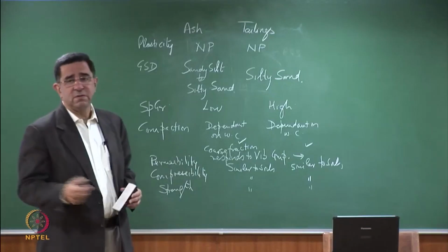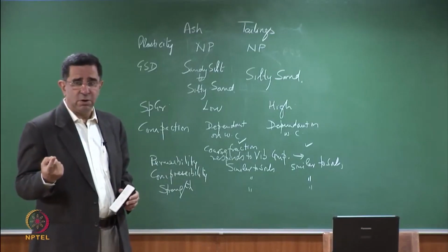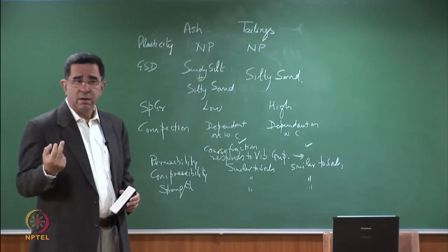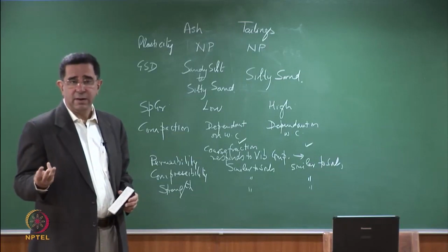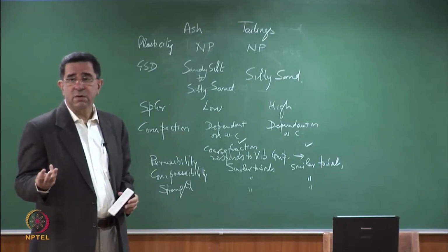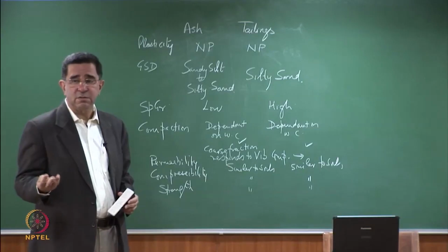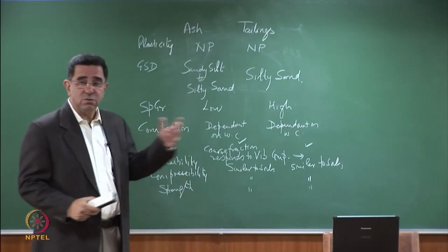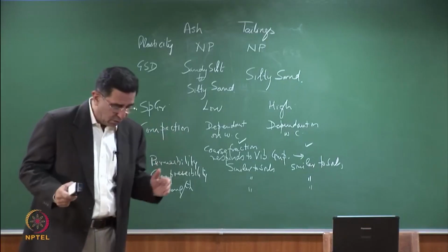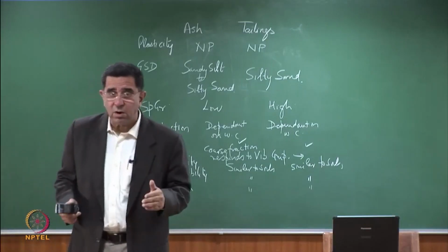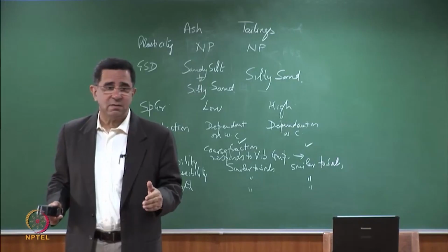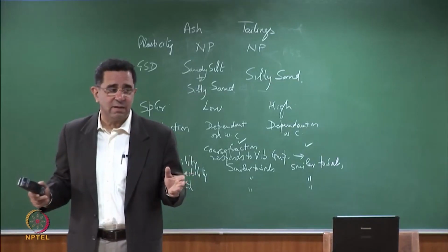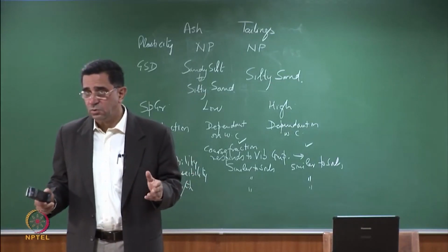So the causes of concern for us are erodibility to rain, dust, and presence of leachable deleterious material. And that we will discuss when we use this for the purpose of design. Whenever we talk that we can reuse this, we are talking of a material which is not classified as hazardous. Any material which gets classified as hazardous cannot be used.